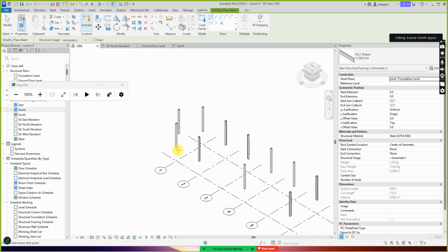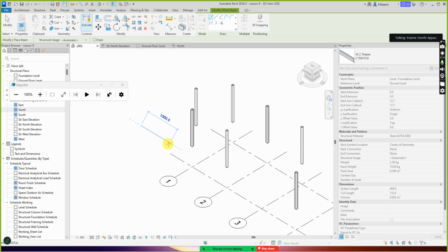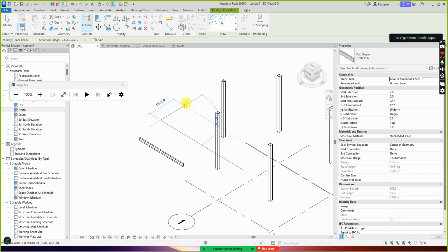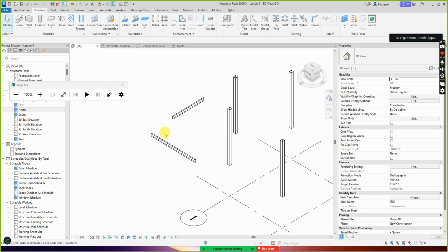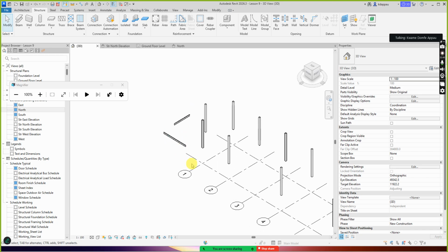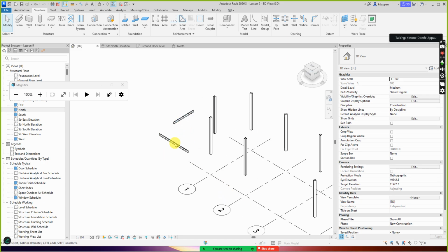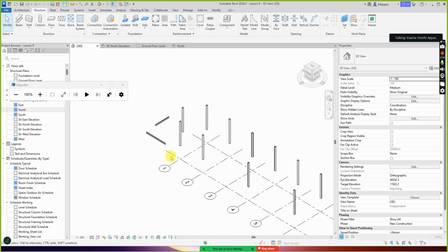So when I want to create a beam from the Revit perspective, I can draw a beam from here to there. This one gives me a beam. It's a linear element. I can also draw a beam from here to here. It's another linear element. It's a beam. But ideally, we don't draw beams in isolation. To coordinate your project very well, you must constrain your beams to grids, so that when the grid changes, the beam will automatically change.